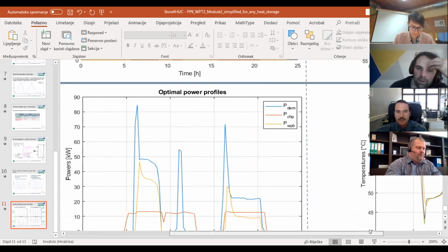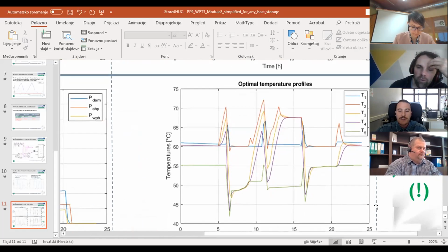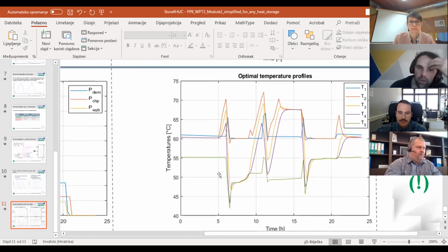While during the day, when the electricity price goes up, refer to this figure, right? Yes, that's right. In the day, when the electricity price goes up, the cost for running the CHP becomes negative. So you actually gain money, but you don't sell the electricity, you use it in the building. But looking just at the heating system and neglecting electricity, it's like the heating system is selling something to the electricity and gaining money from it, right? Something like this.